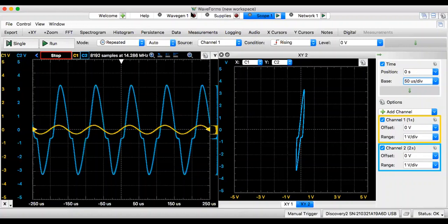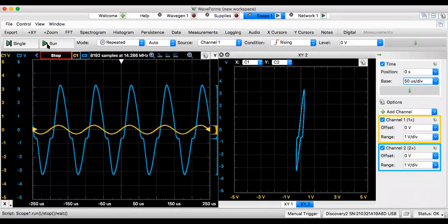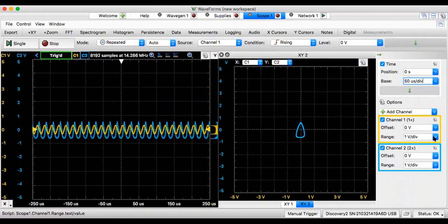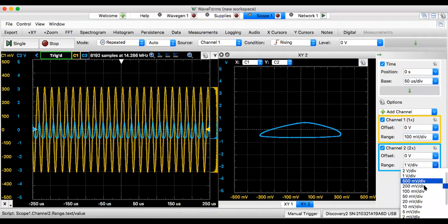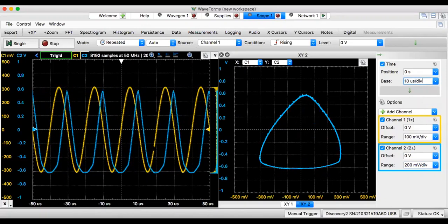The second distortion happens when I increase my frequency to 50K, and we notice huge distortion. So that's my input perfect sine. The output, not only do we not have any gain, we have 0 gain, it looks like. Maybe not 0 gain. The gain is about 2.